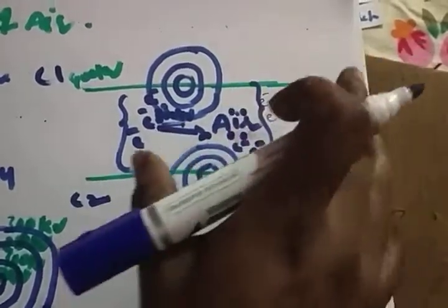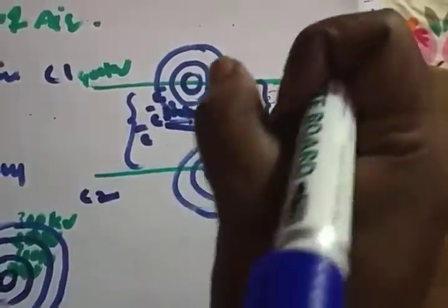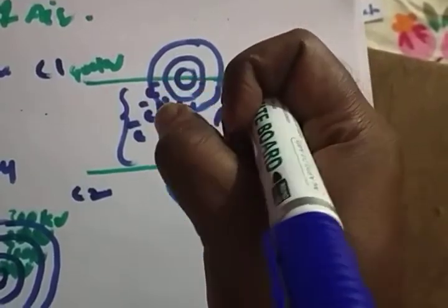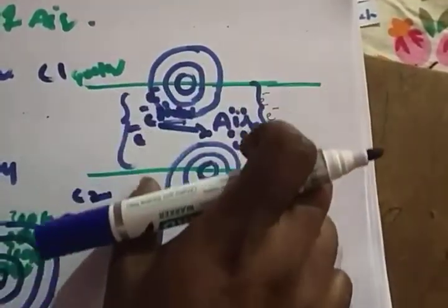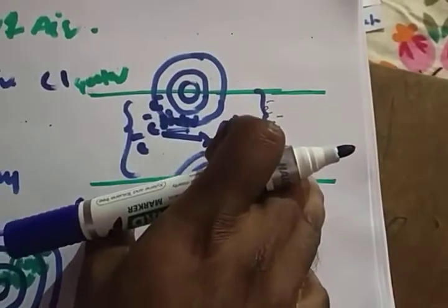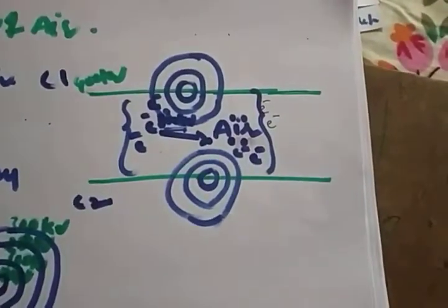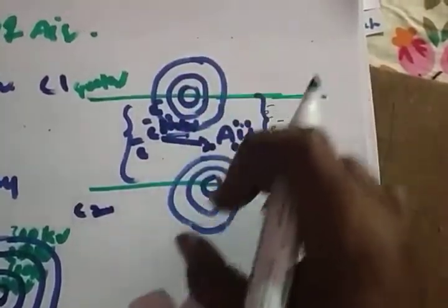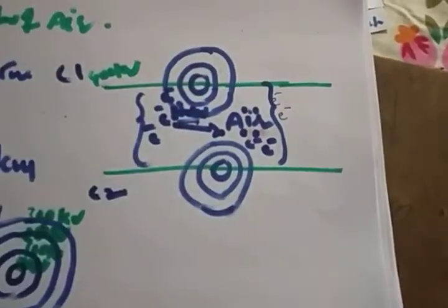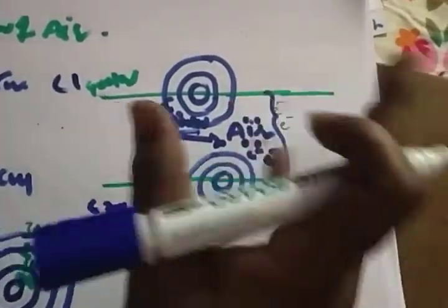Up to a strength of 30 kV per centimeter, the dielectric medium will act as an insulator. Some electrons are going to be formed like that. If it crosses that, definitely the total electrons will be placed between the two conductors, and there will be a conduction path. So definitely some hissing noise will be developed. Some glow will be developed because a charge will transfer from here to here. So there will be a violet glow.